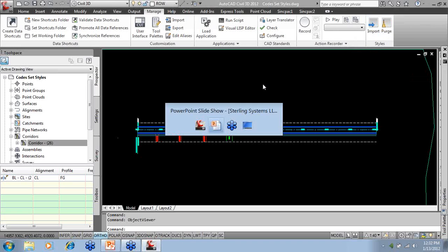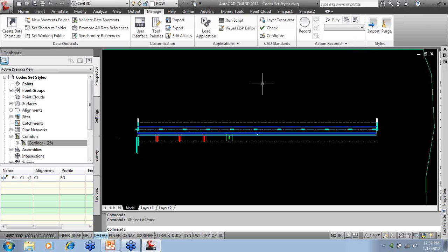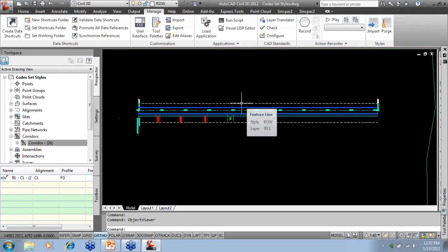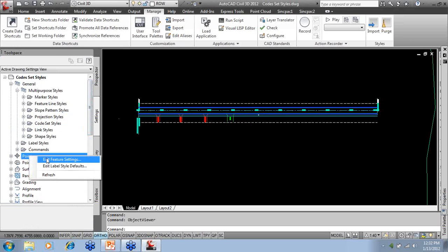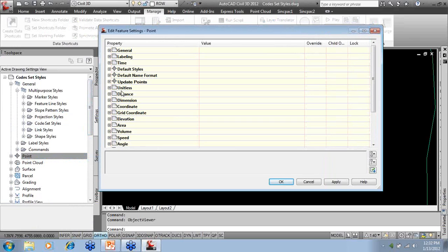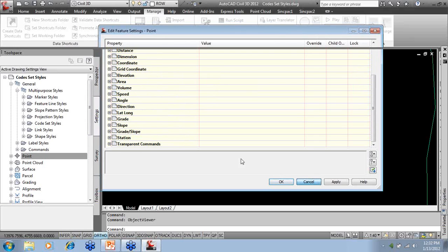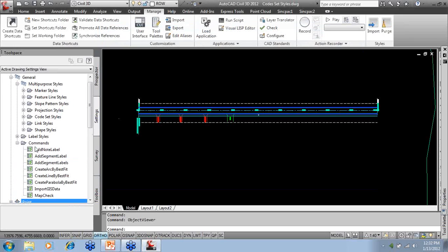A couple other commands just to talk about real quick, I guess, to stay in here. After you delete all the layers, or after you bring in points and you build a surface, you have to reset all the settings. What I mean by that is you go to every object setting, you go to your point settings, and in here, I'd have to look for it, but you're going to have point ID numbers, like point number 1, point number 2, and you just want to reset those.